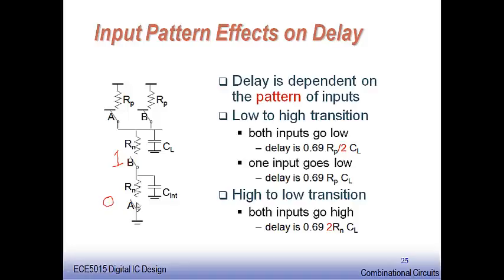Previously it was 1 and this was 0. Because this was 0, when I was charging up this node for a logic 1, this CL was charging, and because this is making this device on, I have even this capacitor charged.